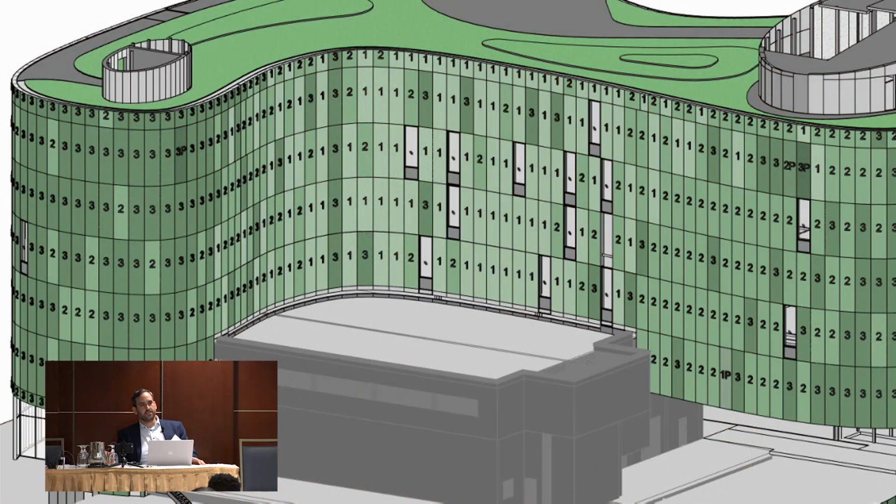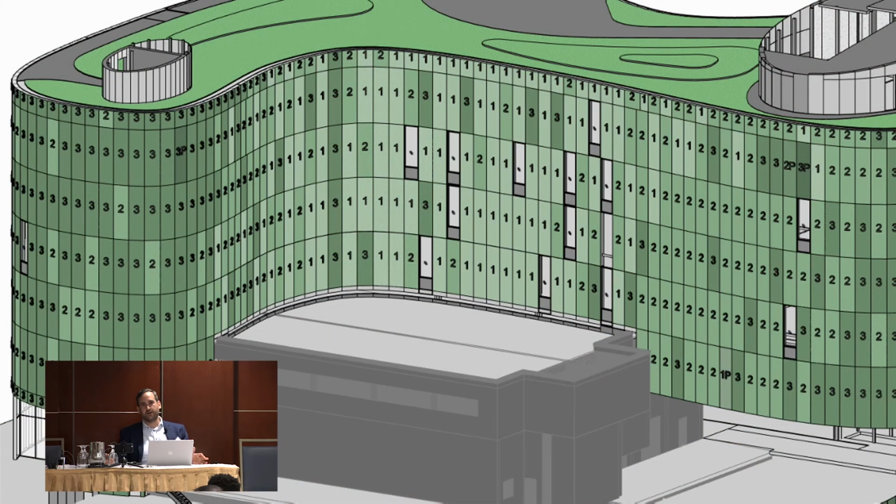One thing that became evident to me quickly as I started testing out the technology is the HoloLens was not going to be clear enough for me to tell slightly different shades of green in the HoloLens apart from slightly different shades of green on site. So we started to think about ways that I might be able to tackle that problem. And in the end, what I did was I built a really simple Dynamo script that placed these generic models all over the building. And they're just telling me what kind of panel it is.